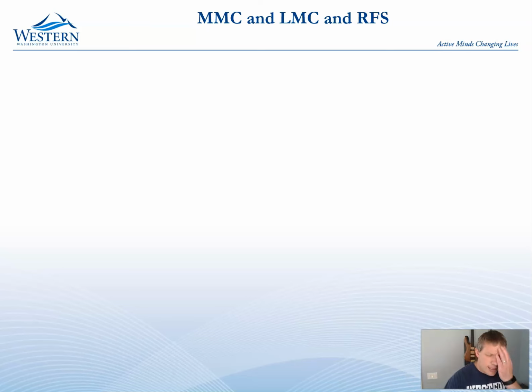However, that being said, I will say in this class and in most of life, the maximum material condition is typically the most useful to use. Why is that? Well, regardless of feature size, we'll look at it in a minute, but it means no matter what size, if I have two pins that need to fit in a hole, so a stepped pin and it needs to fit in a hole, because of the bonus tolerance, the maximum material condition is really the best way to put two things together.